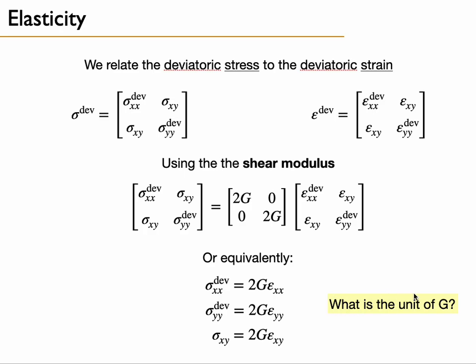So what's the unit of G? Remember that epsilon xx has no unit. Stress is unit Pascal. Therefore, G has to be unit Pascal.